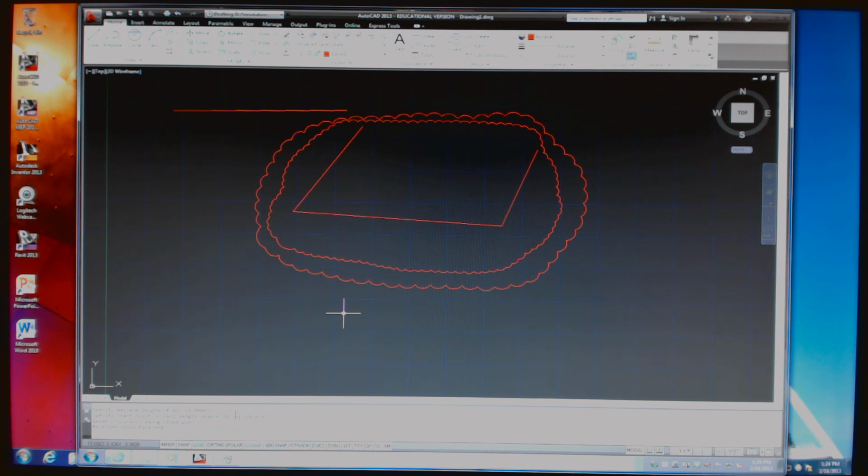But you can Google revision cloud hole in the floor, and it will show you where the guy literally went and cut a hole in the floor to look like a revision cloud. So know when you see a revision cloud on a drawing what it means. Okay, it means there's something being changed.